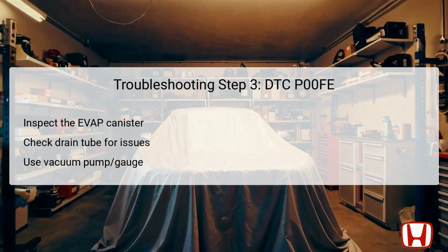If pressure is not held, it signifies that the EVAP canister is functioning correctly. However, if it does not meet this standard, further investigation into the canister for potential blockages or damage is necessary. Addressing these problems is essential for the restoration of optimal function in the EVAP system.